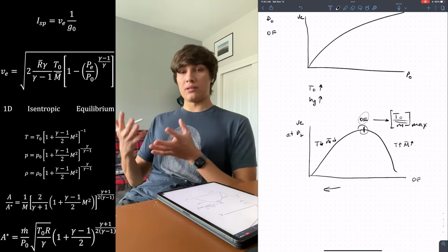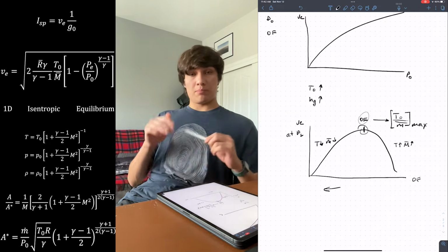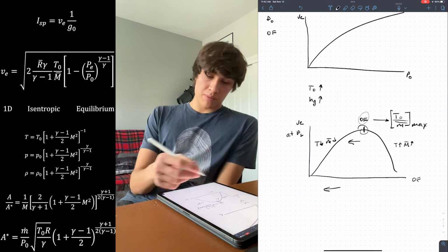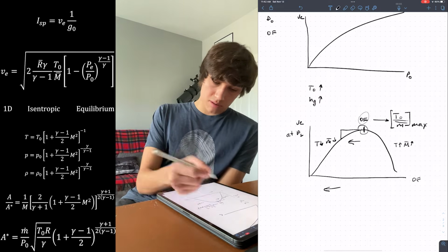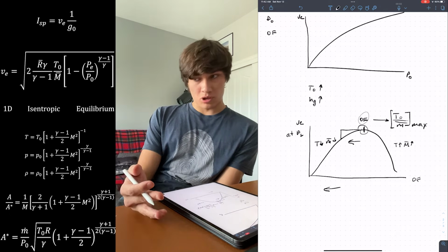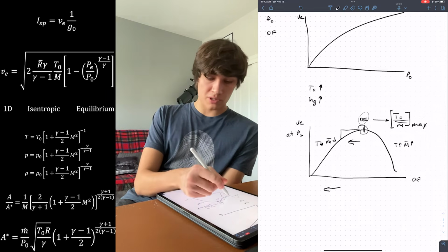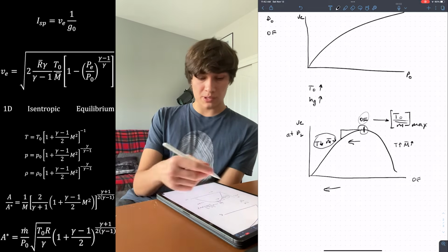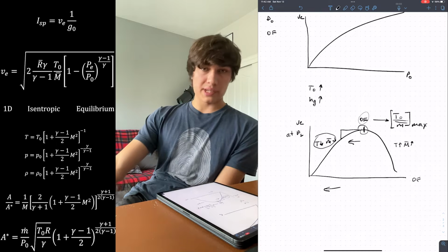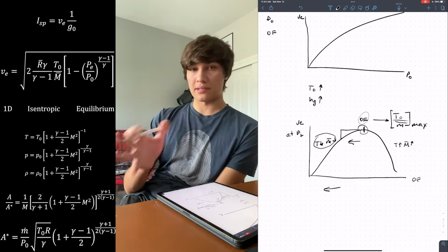Likewise, running at an ideal oxidizer-to-fuel ratio is the best for efficiency, but it might be hard to build. So potentially one strategy is to run fuel-rich, because small decreases in oxidizer-to-fuel ratio will yield small drops in performance, but will significantly reduce the flame temperature, because it's not just the flame temperature that it adjusts, but the ratio of the two. This is something to consider, but when sizing your rocket engine at first, you should find what the ideal oxidizer-to-fuel ratio is and size it off of that.